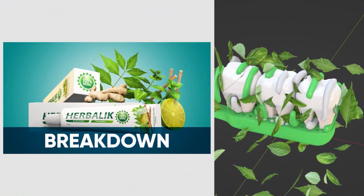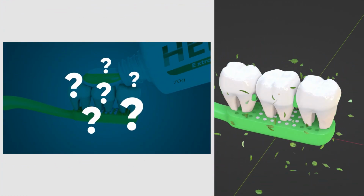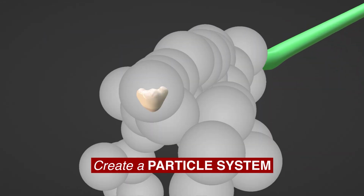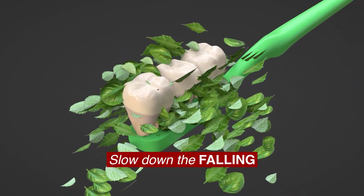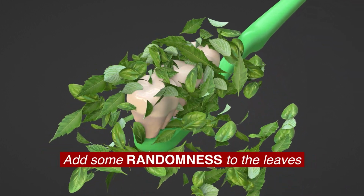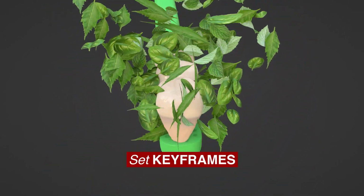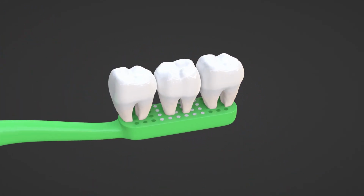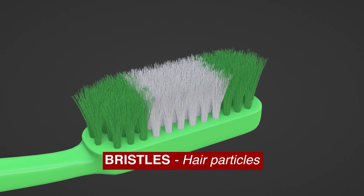I posted a breakdown video of the whole animation, but it did not really clarify how this particular scene was created. We are going to create a particle system, then add different leaves to it. Slow down the falling. Add some randomness to the leaves. Mess with gravity, and finally, set keyframes to decide when to start and end the emission of the leaves. We shall also look into how to create brush bristles with hair particle system.